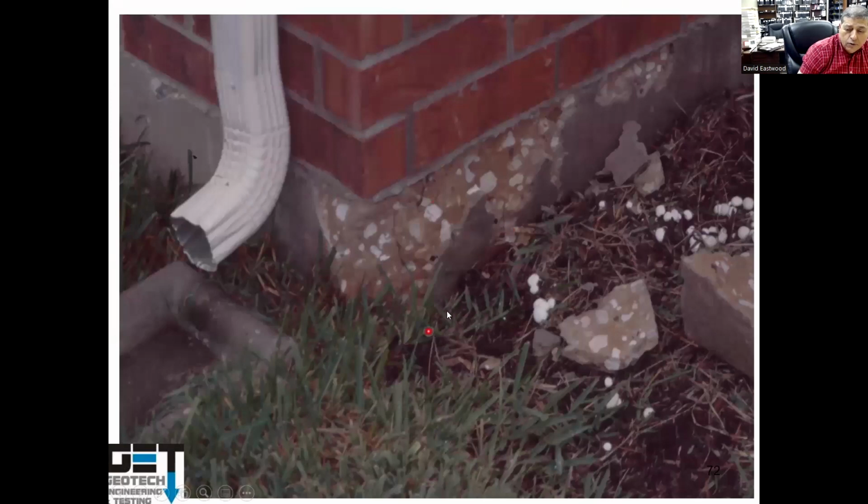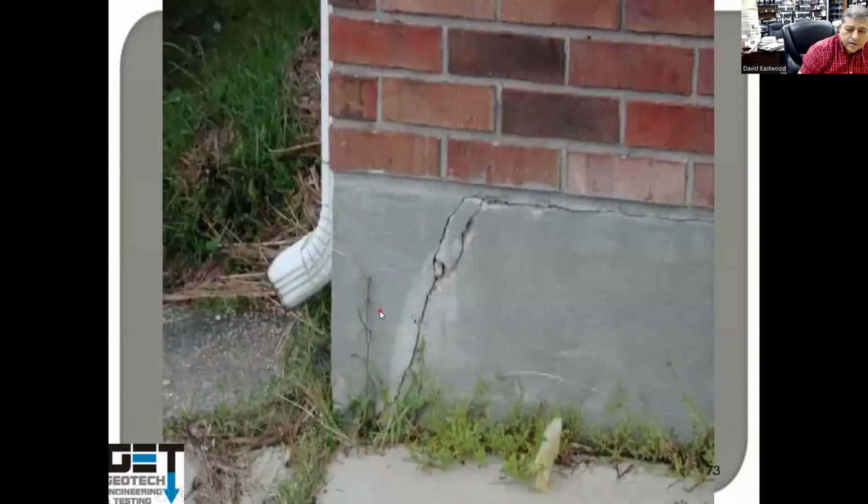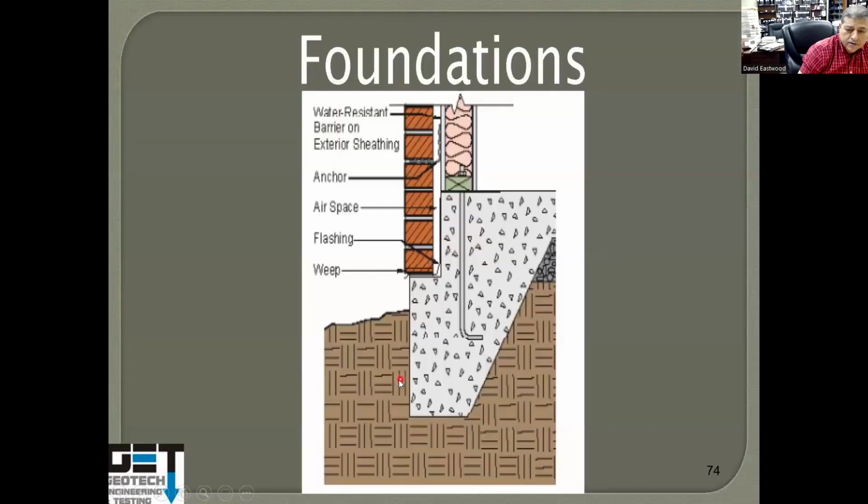Grade beam cracking at the corners. That's because of the absence of a bond breaker between the brick and the concrete beam. Yeah, they moved thermally at different rates, so when there's shrinkage and expansion, the concrete here breaks. It's not structural. It can be removed, and you place a bonding agent there and put in a non-shrink grout and put the grade beam back together.